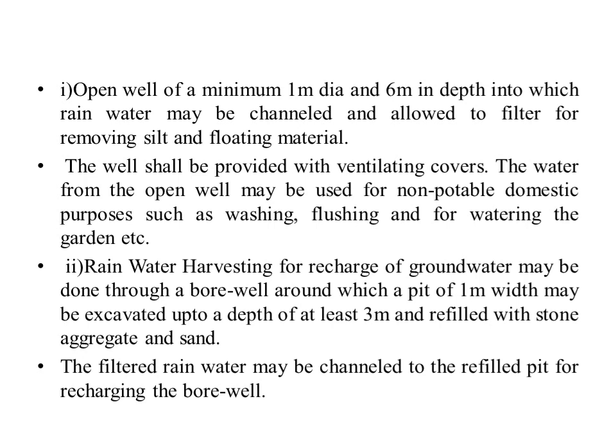Rainwater harvesting system for recharge of groundwater may be done through a bore well around which a pit of 1 meter width may be excavated up to a depth of at least 3 meter and refilled with stone aggregate and sand. The filtered rainwater may be channeled to the refilled pit for recharging the bore well.